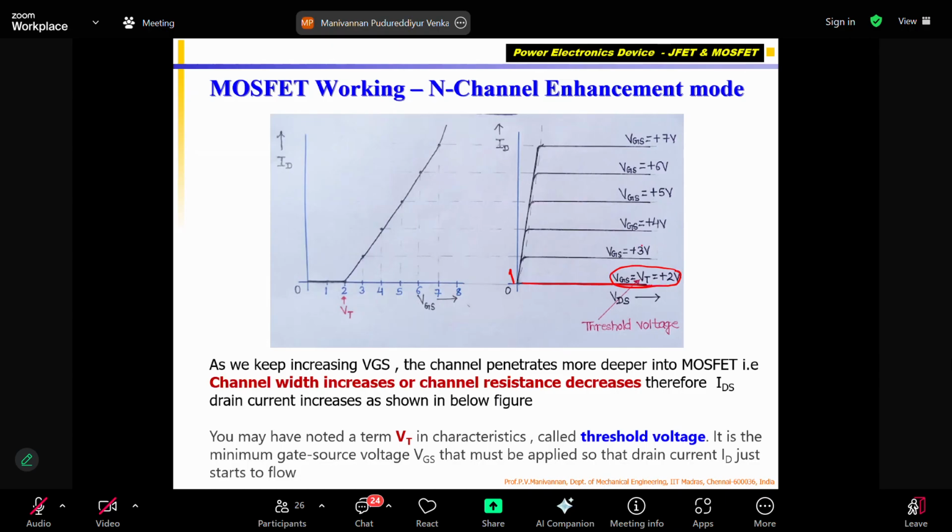Next, I increased my gate voltage to plus 3 volts, because this is an N-channel enhancement mode MOSFET, correct? So that means the gate voltage should be a positive voltage. I gave 1 volt, nothing happened. I gave 2 volts, nothing happened. I increased my drain to source voltage 0, 10 volts, 20, like that up to 100 volts, correct? Still no current flow at 2 volts. So I found that once I give slightly greater than 2 volts, current starts flowing, but I did not draw it here. I took it at the next voltage. You can see that the current starts to become flat.